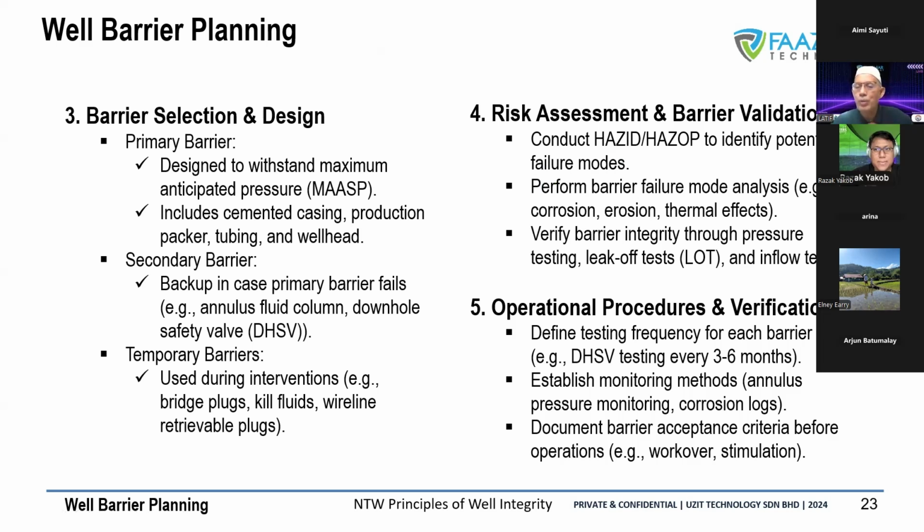So you have to look at all the scenarios and recalculate your condition or your safety factor with the declining pressure. For example, if some casing has eroded, the thickness reduction is about 1 mm per year. You expect that after five years, the reduction in collapse pressure and burst pressure will be about 30%. Because of the reduction in pressure, maybe that is still considered valid, and there's no need for repair. This kind of discussion has to be verified by survey to make sure that your thickness is still within that range.